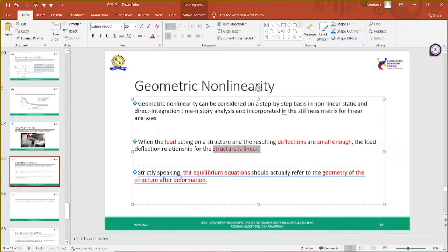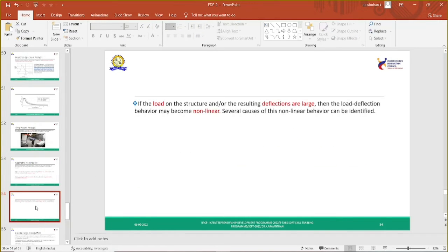When you keep adding floors, what happens? The column gets deflected, and on that deflected member you are still adding floors and still adding columns. So the members are not practically in equilibrium and the geometry is not straight. Now, for small stories it is negligible, and when we analyze I will show you how negligible it is for a small structure, but when you go for a large, tall structure, this P delta effect will be comparable in magnitude and accountable.